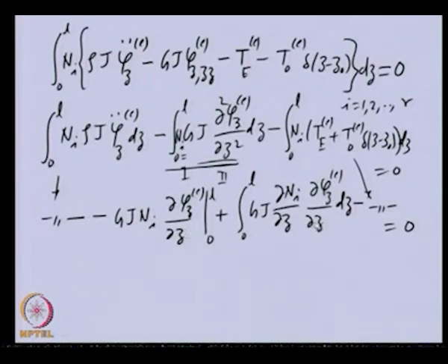So we are now able to use a lesser degree polynomial without compromising on the terms. Even if you take a linear polynomial, the terms will not vanish, and this particular requirement is called the completeness requirement of shape function.